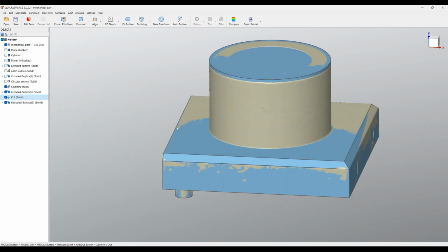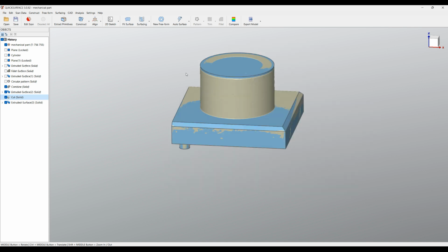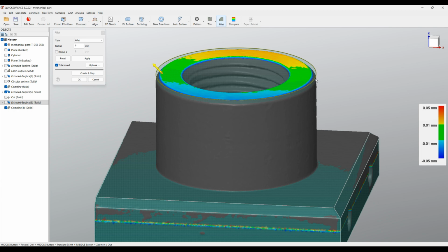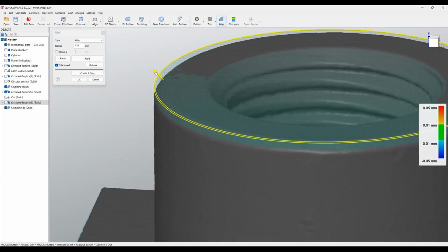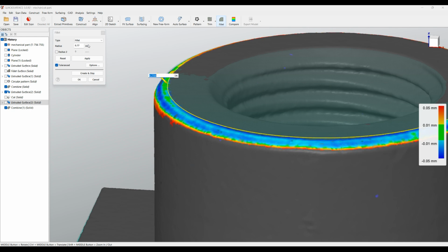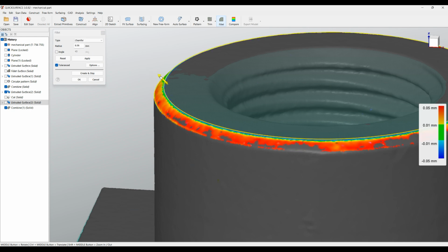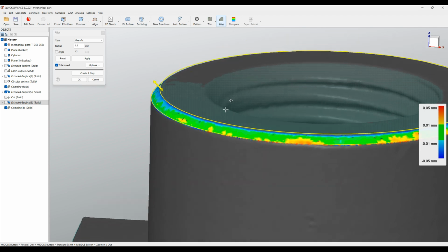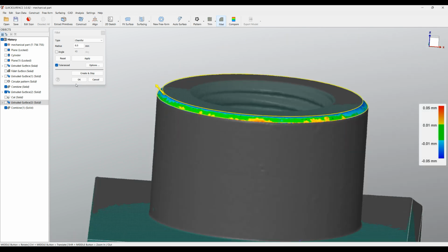We are ready now to create the next step. Again, we'll select everything and select combine. To finish the main body, what we need to do is create a chamfer here. Pick the top face, go to fillet, and we need to select this shape and start dragging. As you can see, it now works with the fillet, but I needed this to be a chamfer. Drag it, see where I get the best result, and as you can see, I'm going to use 0.5 millimeters as this is correct rather than just any random numbers. Press OK.